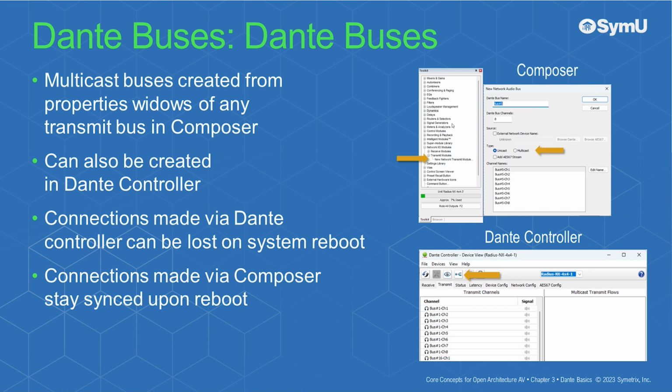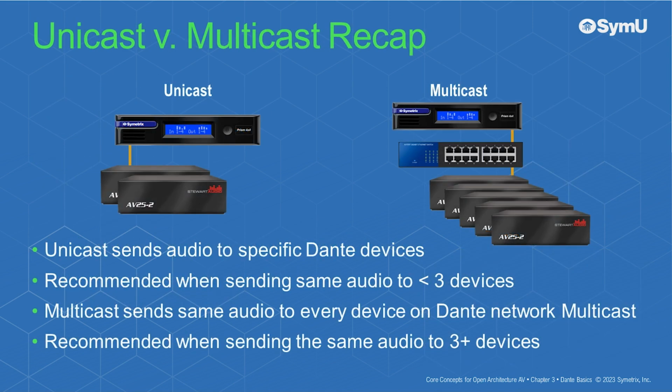All connections made via Dante Controller may be lost when a system reboots, but connections made via Composer stay synced upon reboot. Unicast sends audio to specific Dante devices. This is recommended when sending the same audio to fewer than 3 devices. Multicast sends the same audio to every subscribed device on the Dante network.